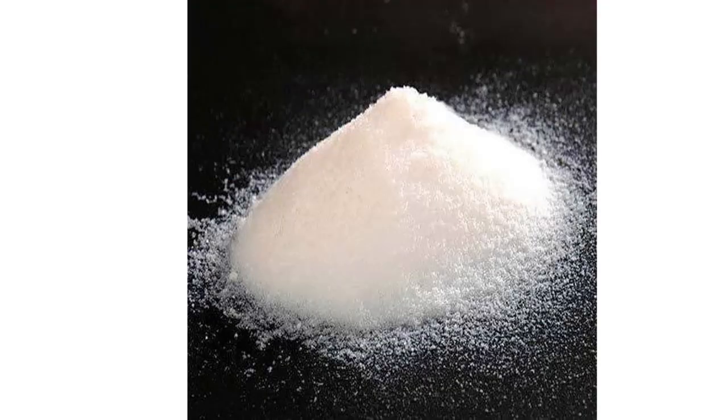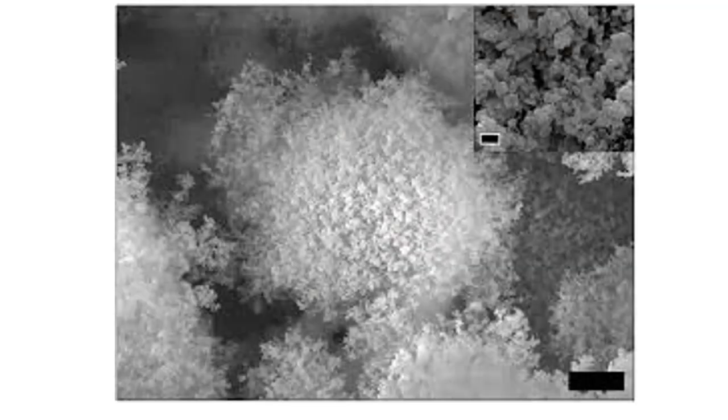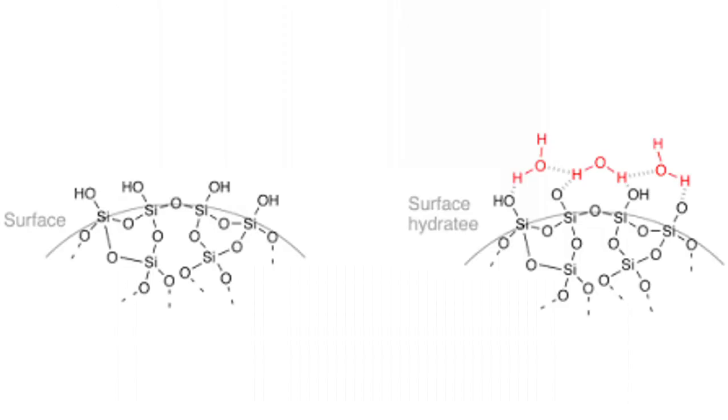Porosity and silica in epoxy formulations. When it comes to silica, its porosity plays a crucial role in modifying epoxy adhesives and coatings. Highly porous forms of silica, such as fumed silica and precipitated silica, contribute to thixotropy, reinforcement, and improved adhesion properties in epoxy formulations. Understanding how porosity influences silica's behavior in resins will help us make better material choices for enhancing viscosity, mechanical performance, and stability.